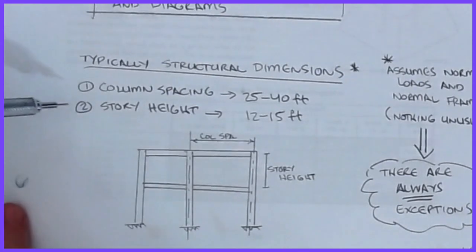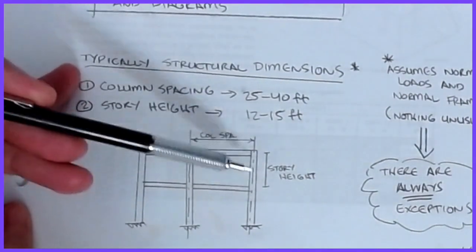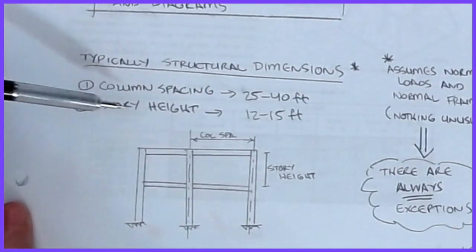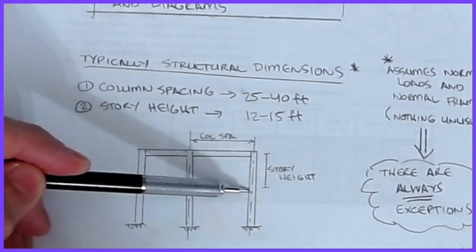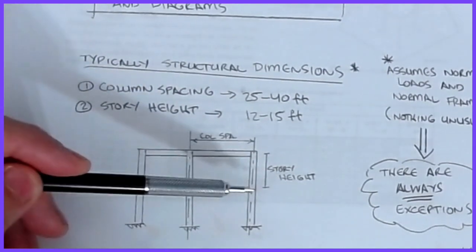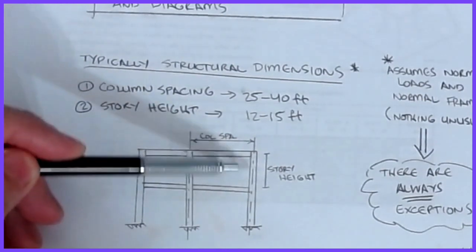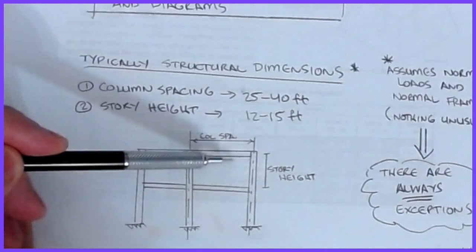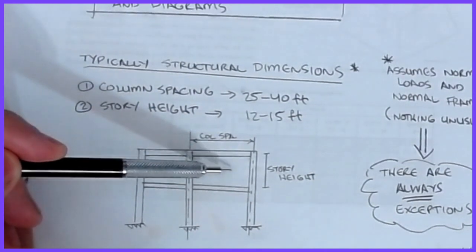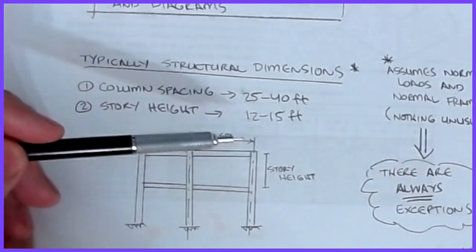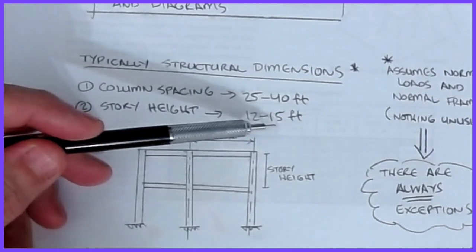Okay. The other rule of thumb that I use is that between floors, which is what we call the story height, typically that's somewhere between 12 and 15 feet. Now, I define story height as the top of floor above to top of floor below being that distance. So in that space, you have, say, the thickness of the beam, I have the clear height, and if you have anything like a drop ceiling or anything that brings that ceiling line artificially down, then you can quickly eat up into this. So I tend to prefer to push more towards 15 feet.